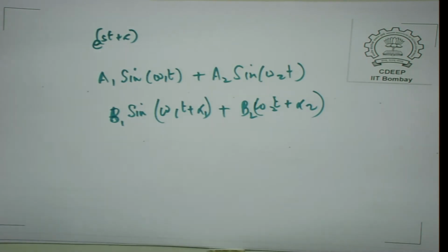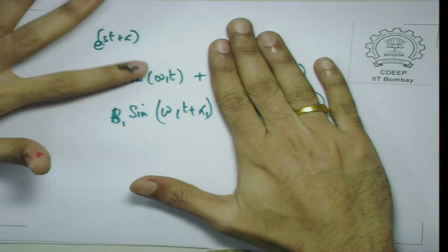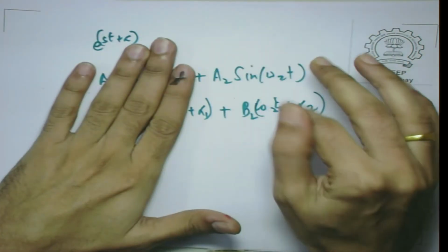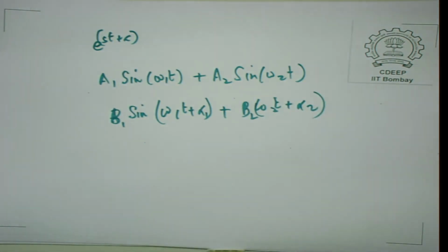In nonlinear circuits, if you excite it with sin omega t, even though you may reach a sinusoidal steady state, even if you excite it with one frequency, in the periodic steady state you may find 2 or 3 frequencies or more. That is interesting about nonlinear circuits, but for linear circuits there is a causal relationship between this and this and this. So, in fact, you can get what is known as the frequency response of the circuit quite easily.